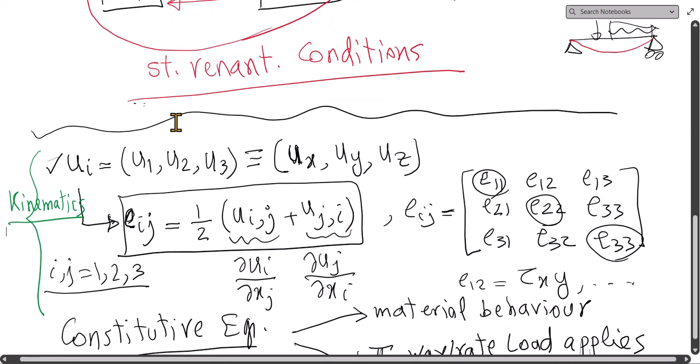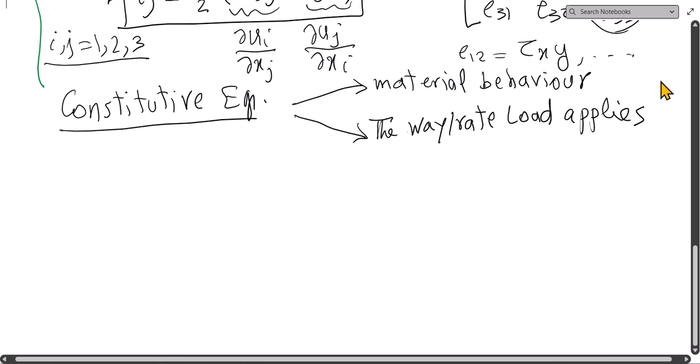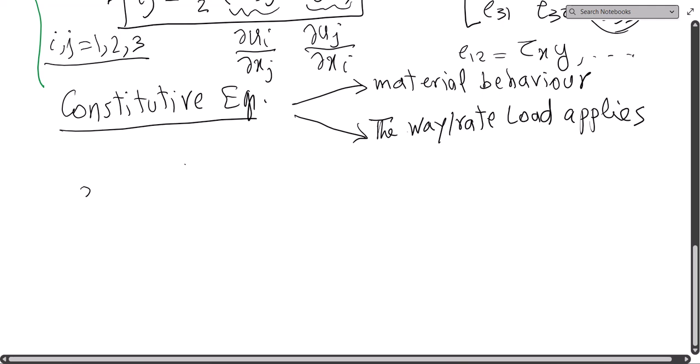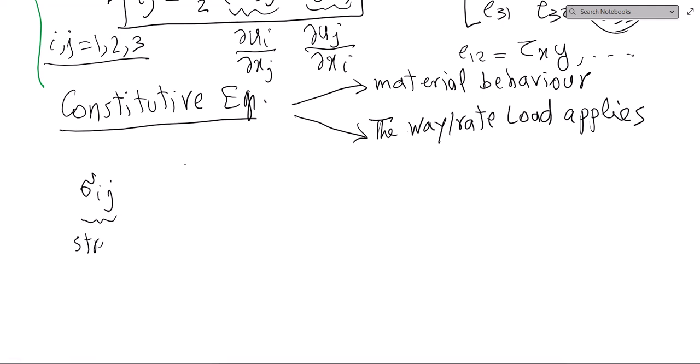But now we want to arrive at kinetics. When we talk about force and stress, we arrive at the zone of kinetics. So in beams and in solids, what we use is sigma ij, which is the stress. Immediately you should notice that sigma ij has two free indices, so it has 9 components in three-dimensional space.